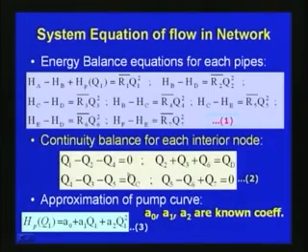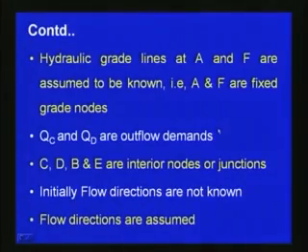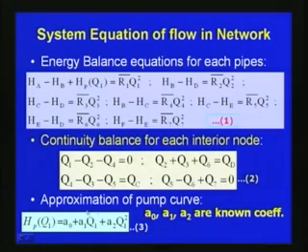And then as far as the pump is considered, here we have got a pump at this location. So, for the pump we can write an equation like this: HP of Q1 is equal to A0 plus A1 Q1 plus A2 Q1 square, where A0, A1 and A2 are known coefficients.